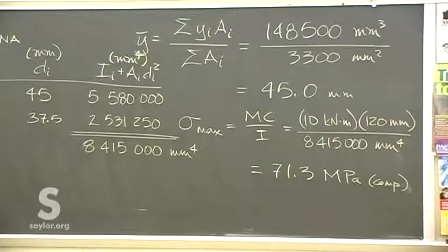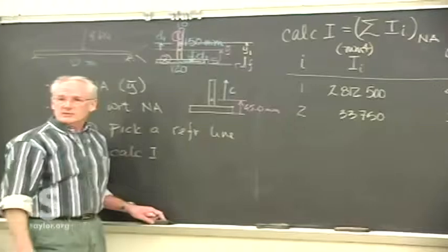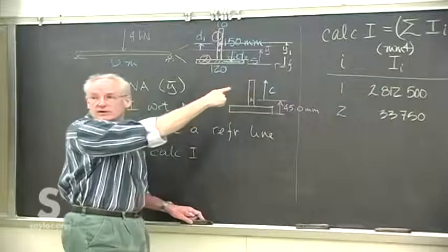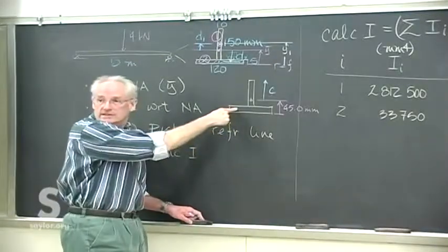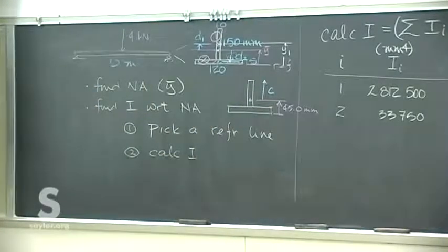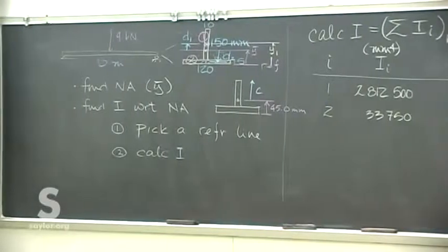And the bottom, I think, comes out to be, what is that? Oh, that's just the compression, the value of 2 points we don't need. Which, if this is wood, it would explain why they use this cross-section of a beam. Wood is very good in compression, so you don't necessarily need very much wood at the top. It's not very good at tension, so you're going to need a lot more material down there for the wood to resist the tension at the bottom. A number which I don't happen to have.